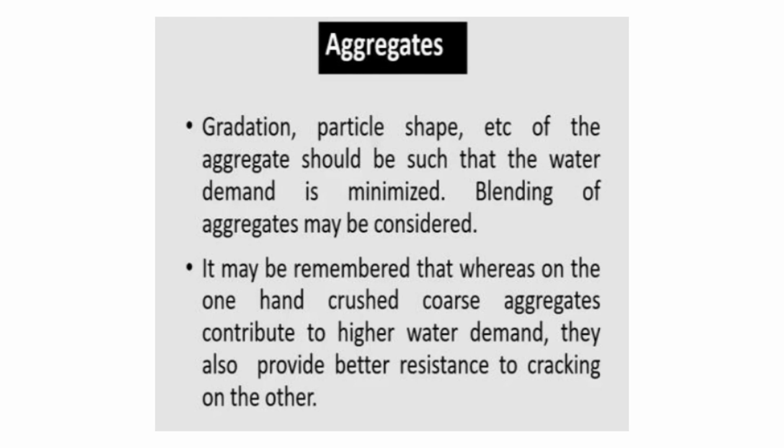Okay, so which can be like some green materials, waste materials. It may be remembered that whereas on the one hand crushed coarse aggregates contribute to higher water demand, they also provide better resistance to cracking on the other. So this is a tricky situation.